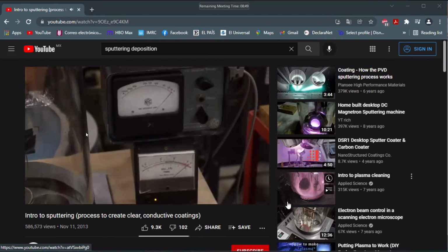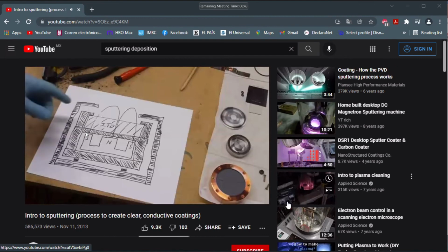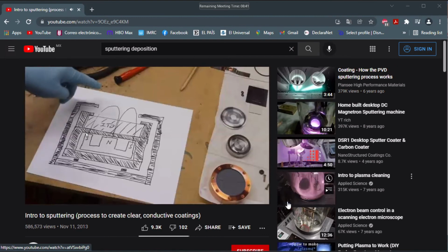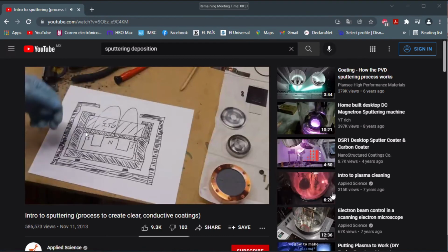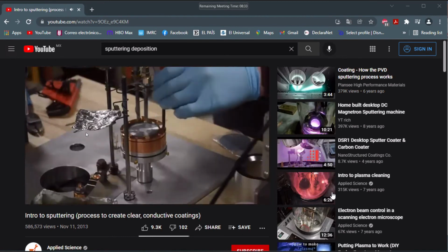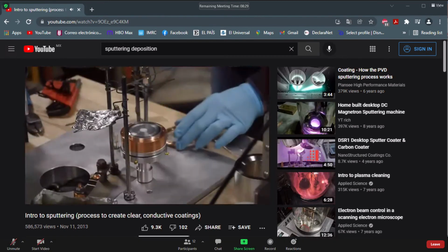However, the high pressure is such a good conductor because there's so many ions, it's tough to get the voltage high enough, so the incoming ions are going too slow to cause the sputtering to happen. You'll have a nice glow discharge and things will look like they're working, but you just can't get the voltage high enough without blowing everything up basically.